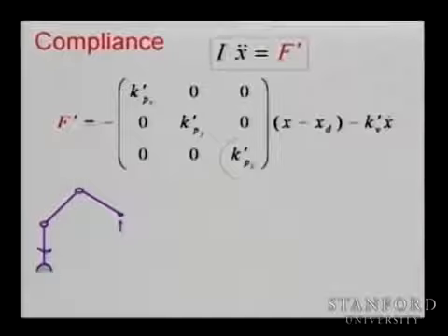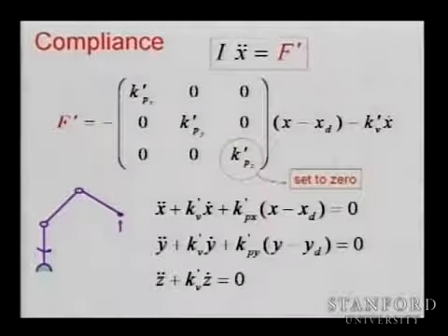I'm sorry? Doesn't it just stay where? Well, if it is 0, it is basically free now. That spring is cut. So you move it, it's going to move. From the control we developed for the position, because we have a control in x, y, and z in task space, the end effector is stiff in this direction, stiff in that direction. In this direction, if you change kp and make it 0, now it's free. And just by making kp equal to 0, you are going to have those relations.